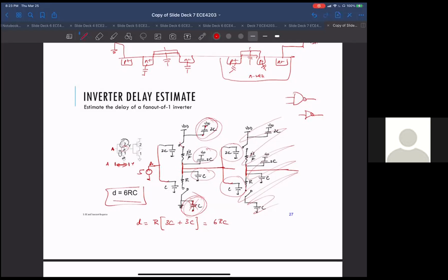Okay, thank you. That makes sense. Sure. Wait, actually, go ahead. Sorry. To follow up, in digital design software, would that level of control be abstracted away? Yeah. A lot of times, even in SPICE, there are 4 terminal models for NMOS and PMOS where you show the substrate connection, and then you'll see 3 terminal models. Whether you're using LTSPICE or PSPICE, you'll probably have in your library a 3 terminal model for NMOS and for PMOS, where they've assumed the substrate to be connected to VDD or whatever. Same with logic gates. The logic gates already assume everything is connected up to VDD or ground. Okay, so they are abstracted away. Yeah. Okay, thank you. Sure.